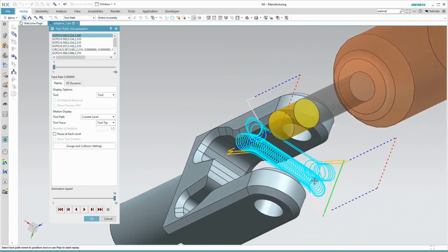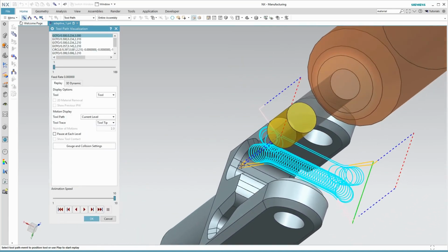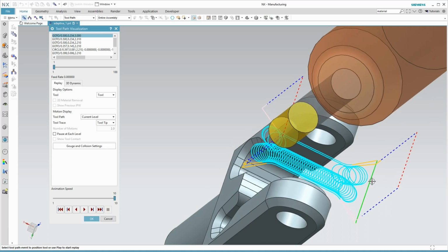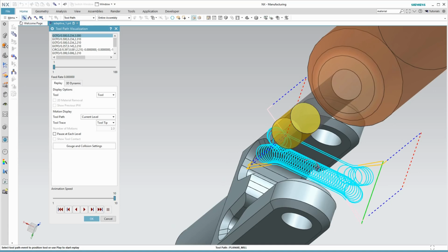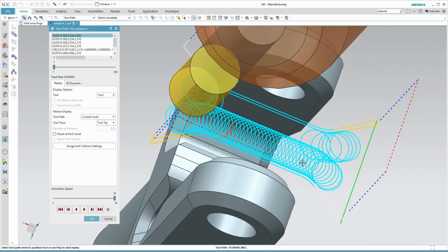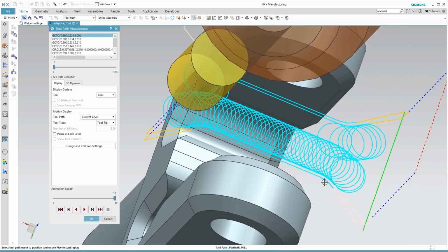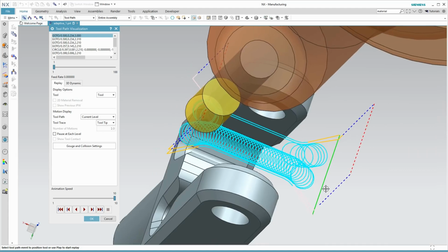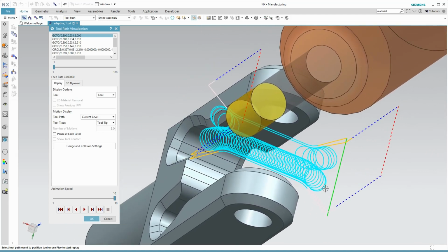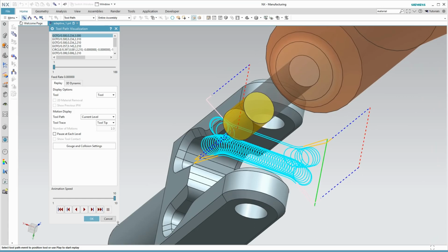Here I'll show just one of the levels, but it's a pretty straightforward application where the trochoidal cuts go through on one side, and then a more conventional type machining goes through on the other. This particular operation is also using the finish pass option, where we're leaving 5% of the tool diameter as finish stock. Now, our adaptive machining operation does not have that finish pass option, so we'll be creating a second operation to do that with.